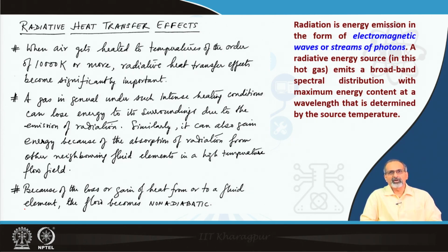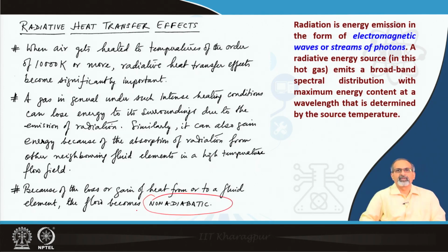Because of the loss or gain of heat from or to a fluid element, the flow becomes non-adiabatic. In many of the flow problems of interest in compressible flows that we have been discussing till now, we have been making the assumption of adiabatic flow. However, that breaks down completely when we discuss radiative heat transfer.